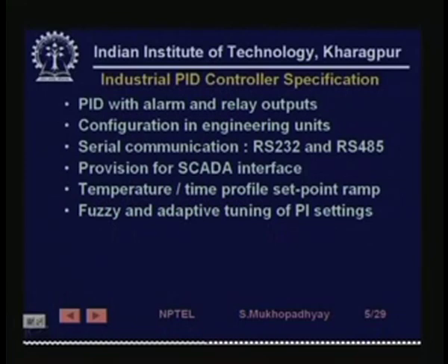So, in such cases, for efficient response as well as for things like energy efficiency, you need to tune PID controllers from time to time, and so they have provided algorithms for doing that using, you know, fuzzy means there is a special technique called fuzzy set theory, which is used to design controllers. So, you can have fuzzy and adaptive tuning. Adaptive tuning means that the controller continuously keeps adapting as the plant changes. So, you could choose one of these to get the PID settings.